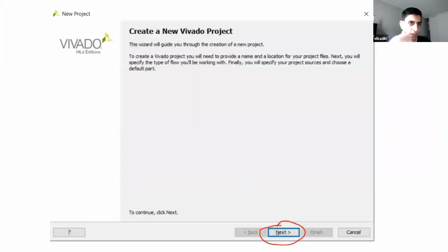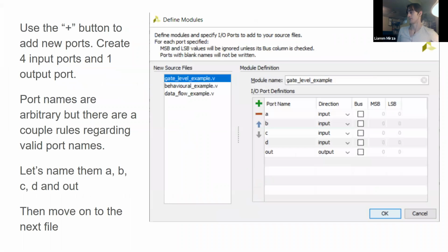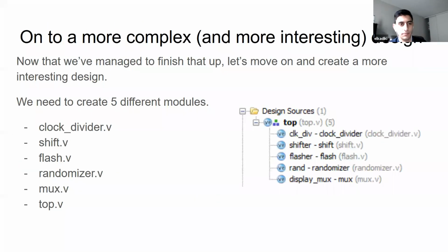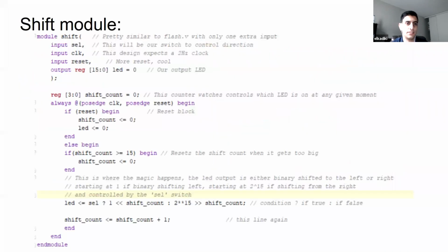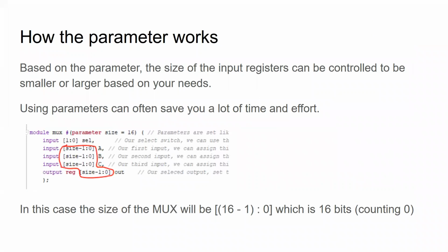So it'd be the same thing. It doesn't change functionality. It should still be one of the buttons labeled. We're not resetting the whole FPGA. We're just resetting our design. So the CPU reset, we can't access that pin because that's actually on the board. We can't control the CPU reset. But the reset that we have should really be called soft reset.